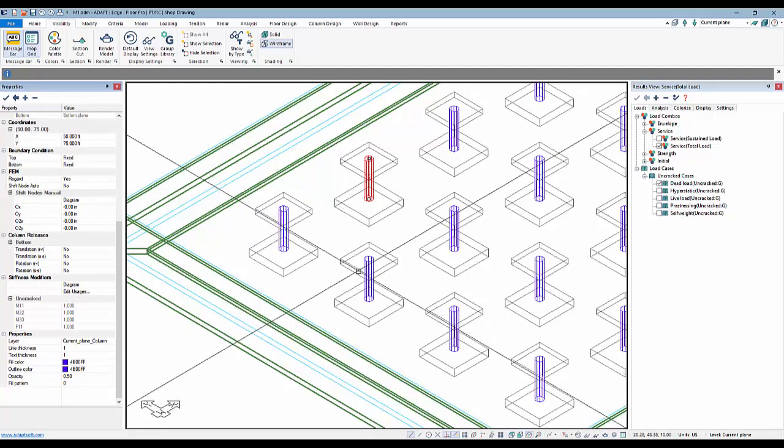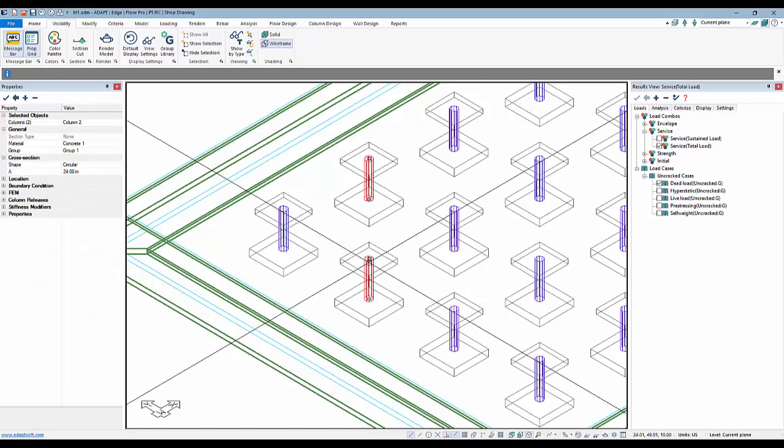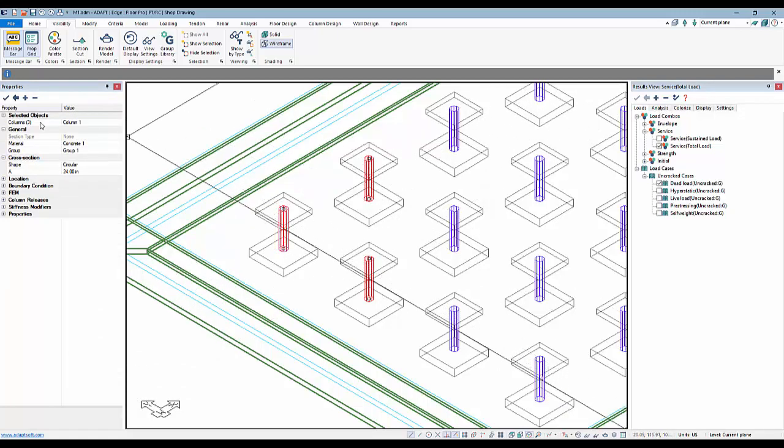For multiple columns, I can do the same thing. If I select multiple columns, you can see this includes the count of the columns selected. So we have 4 columns now. Because they have a unique component, let's say cross-section shape, this is 24 for the entire group. I could select that for the group. If these had different cross-section shapes, then this is dashed out.